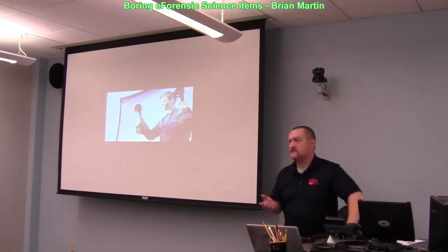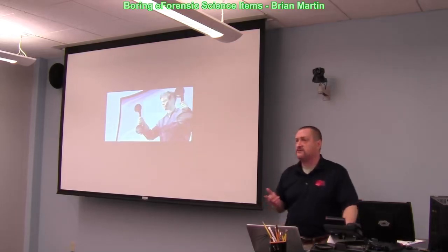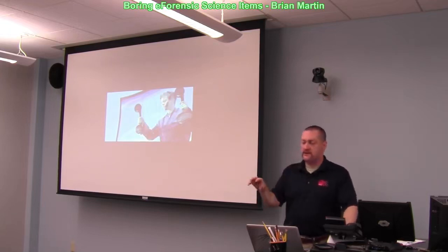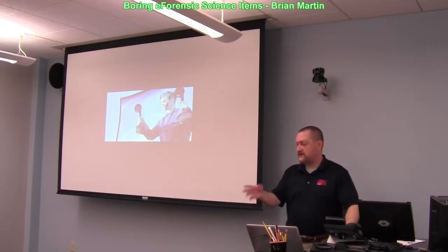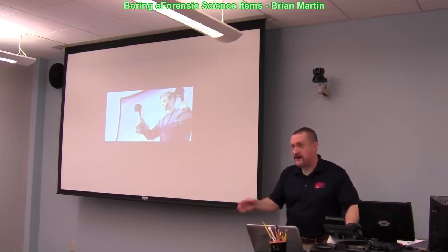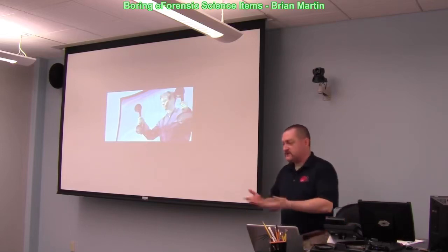So like I said, when we come across a problem in the processing, we just replace the part. We don't question why. And from an electronics engineering viewpoint, this is one of the worst possible things you can do. Because if you replace that card and you haven't figured out why that card didn't behave, or worse, why that card failed, you may have just fried your second card. And I've literally watched engineers go through boxes of hard drives and boxes of cards before someone said, it might not be the cards. It could be your motherboard, or it could be your power supply, or something intelligent like that. So most of the time it's a trivial cost.